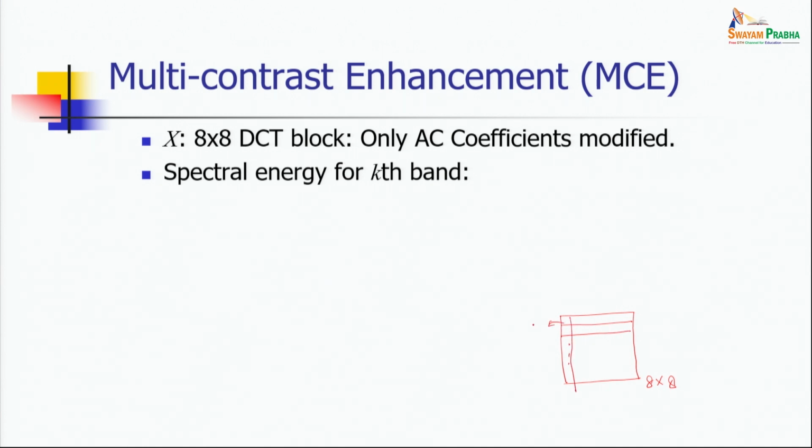So as I mentioned, this is the DC coefficient position. This is a 0 element. So this is the DC coefficients. Now the rest of them are AC coefficients, and there is a particular order by which these coefficients are scanned, because of their frequency, the order of frequency will also be increasing. So it's a zigzag order. In fact, you can see these are all off diagonal elements.